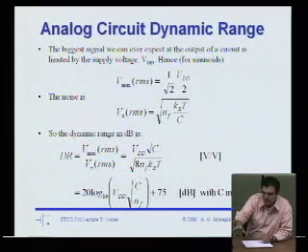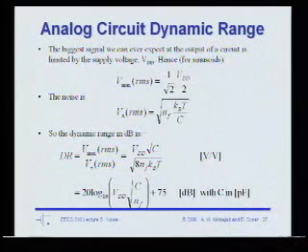I'm not sure where we stopped exactly last lecture, so if I'm going too fast, just slow me down. But again, this is just another slide that illustrates this point, that if you want to calculate the dynamic range of an analog circuit, you could say that for the most part your signal swing is determined by your supply, right? There's an overdrive factor that comes in there, right? But the first order, it's VDD over 2 if you're not using any inductors. The noise, as we've seen, goes something like KT over C, noise variance power. So noise voltage, total voltage noise, goes like square root of KT over C.